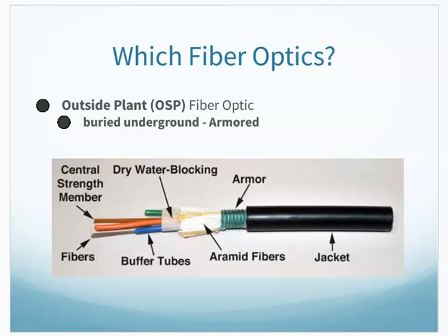If you have fiber optic cable buried underground, you would typically have armored cabling. So you have the jacket, and then it's kind of like a thick foil shield, and it's there to resist a couple things: water, damage from the weight of material on top of it, but also to resist critters chewing through. Critters tend to chew through things. If you've ever dealt with mice or squirrels or whatever, you know what I'm talking about. Critters will chew through your fiber optic cabling. So this cable is designed to be buried underground.